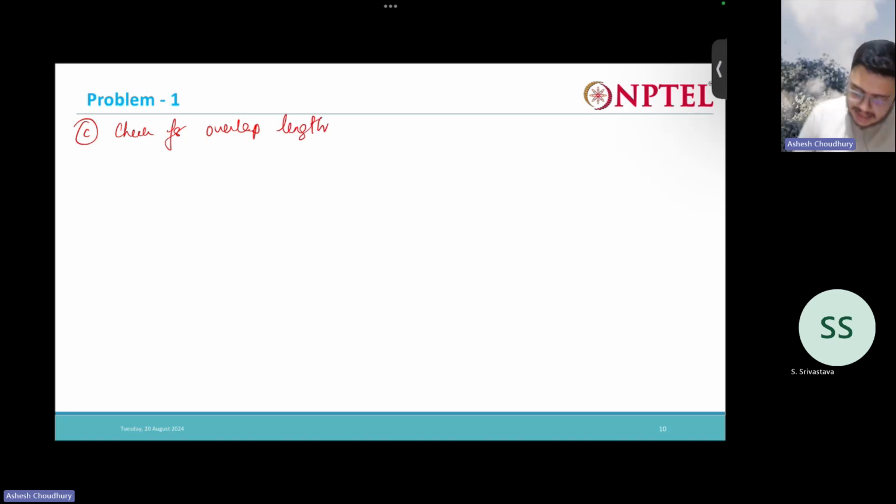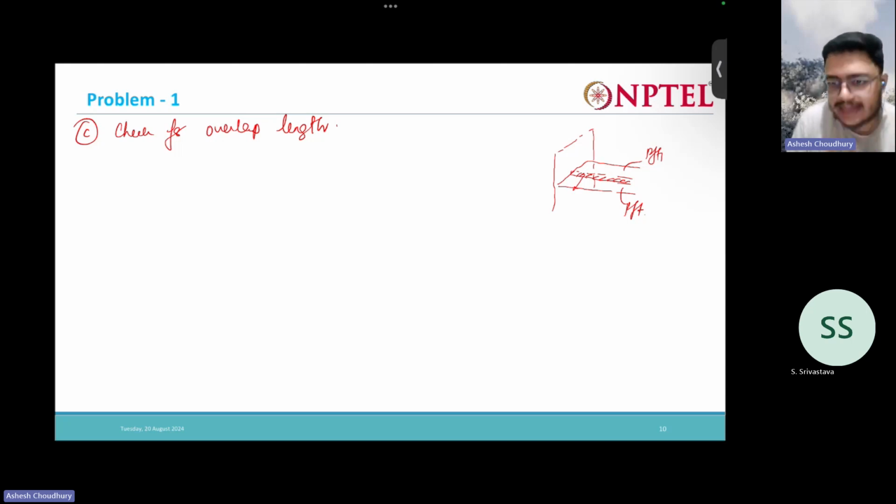Overlap. So say this is the wall, and like this you are placing the geotextile, then in this direction the width will be less, right? So you need to use one more geotextile like this and overlap it, so this first portion will be overlapped. This is RFT1, say this is RFT2, overlap. So that we have to do. This calculation is almost similar to what we did for the embedment length calculation.